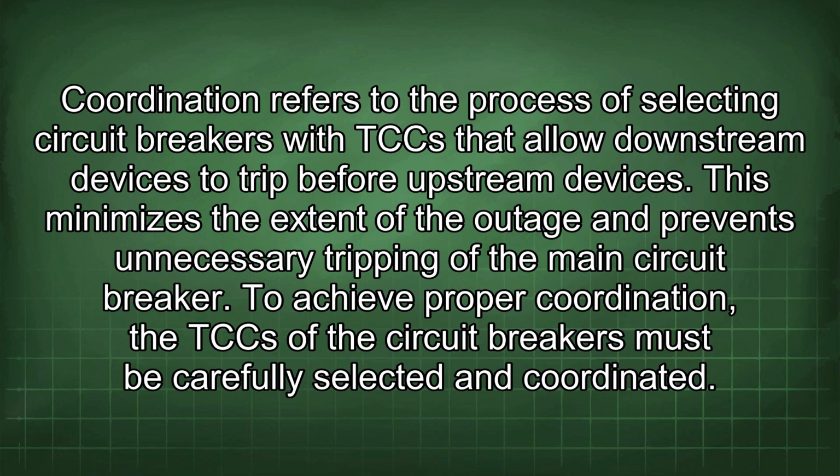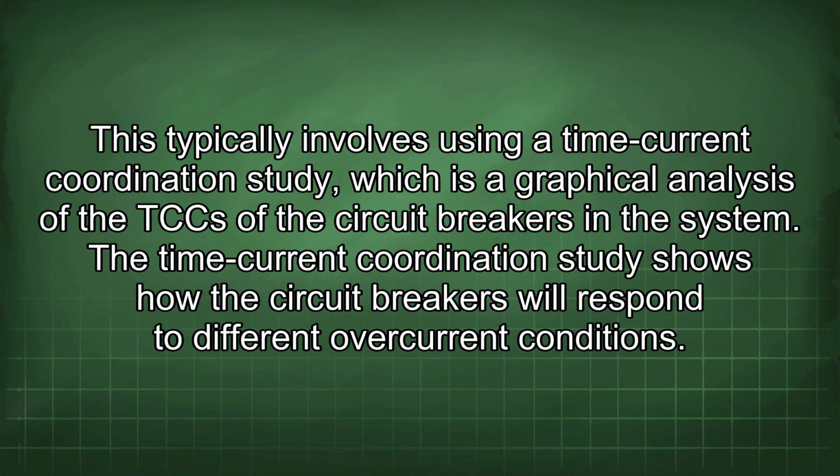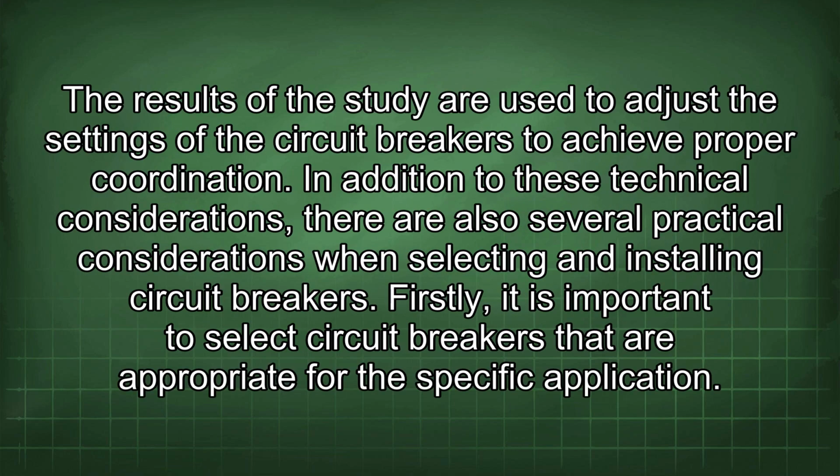To achieve proper coordination, the TCC of the circuit breakers must be carefully selected and coordinated. This typically involves using a time-current coordination study, which is a graphical analysis of the TCC of the circuit breakers in the system. The time-current coordination study shows how the circuit breakers will respond to different overcurrent conditions. The results of the study are used to adjust the settings of the circuit breakers to achieve proper coordination.